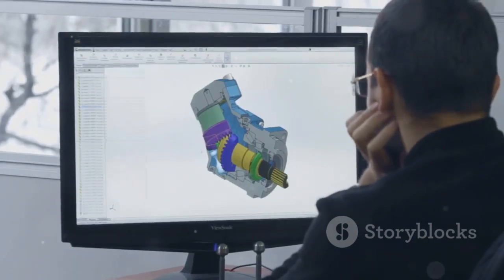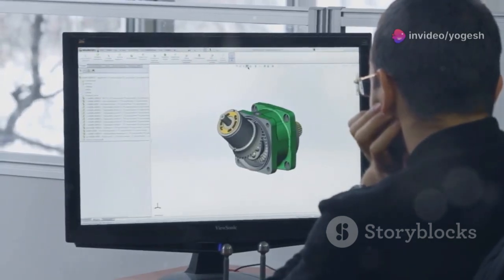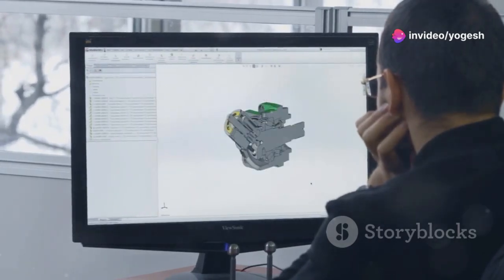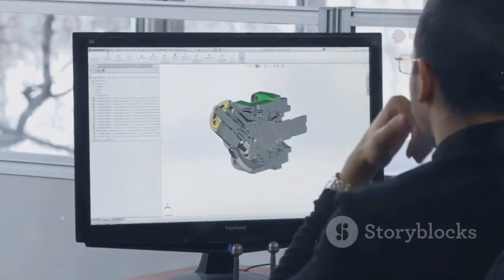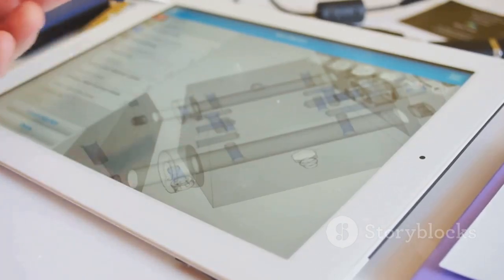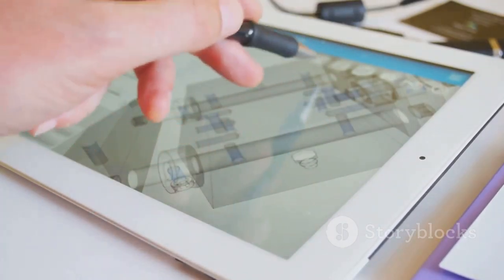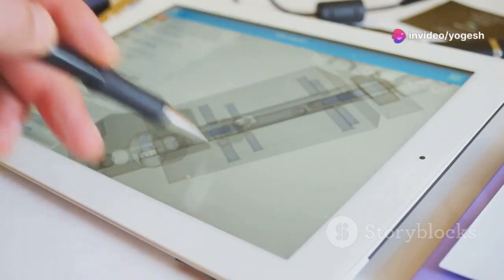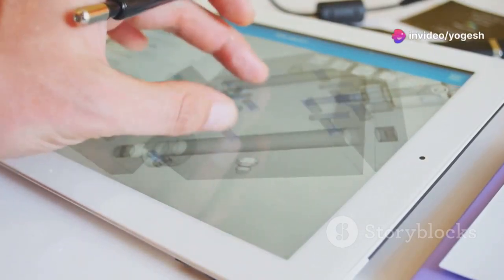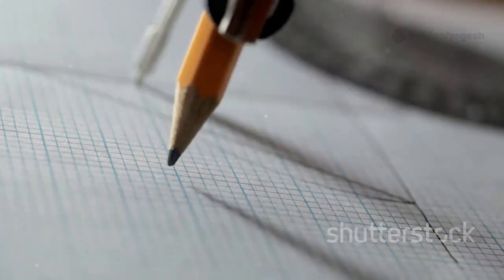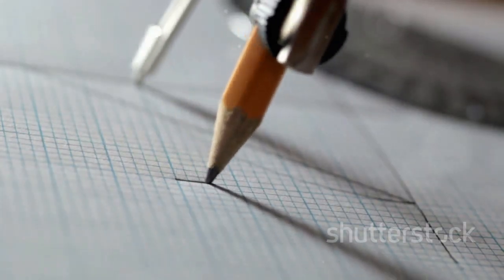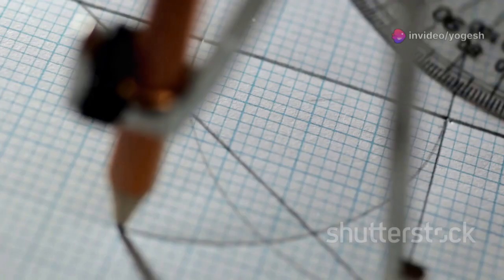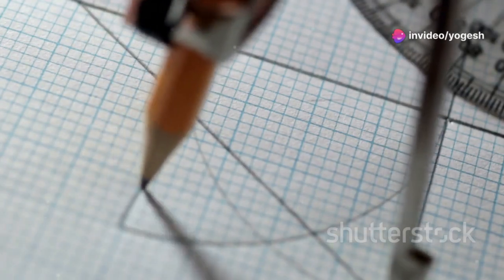These points guide the path of the curve, allowing it to bend gently in one area and tightly in another. The more control points you add, the more detailed and flexible your curve becomes. In CAD, the software uses these points to create the smoothest possible line, automatically calculating the best path through or near each control point. This makes splines ideal for complex shapes in organic forms. Unlike a simple arc, a spline can change its curvature continuously along its length. This means it can flow smoothly from tight bends to gentle sweeps, all in a single curve.